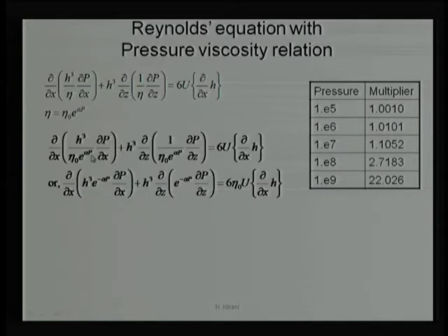In this case we know very well alpha p is here and p is here also. So, this is a highly nonlinear term. It will be difficult to solve. That is why we require some sort of mathematical manipulation, rearrangement, substitution. Let us assume one quantity q and name it the reduced pressure, and the expression of reduced pressure is q equals 1 minus e power minus alpha p, divided by alpha. Now, what is the advantage of this term?